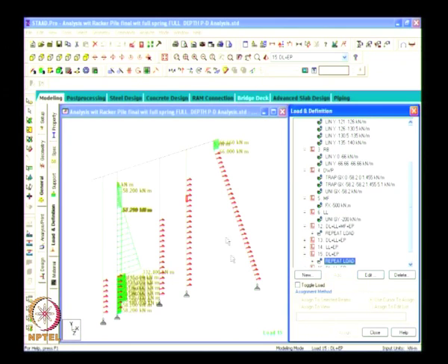The live load means stacking of some cargo and other things. This may come at some time, this may not come at some time, but permanently your soil will be here, your weight of the structure will be there. So we have to do this for dead load plus earth pressure, that is shown here. So here we have listed the various load combinations.